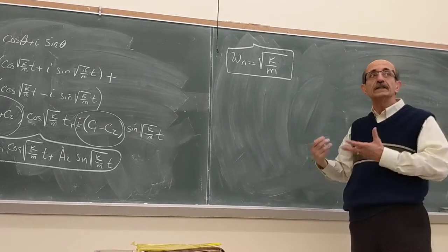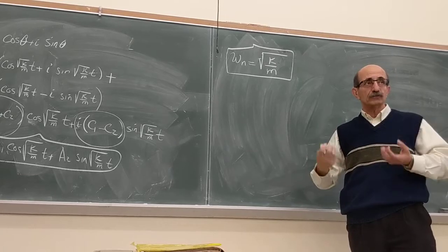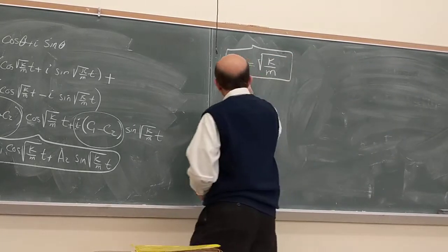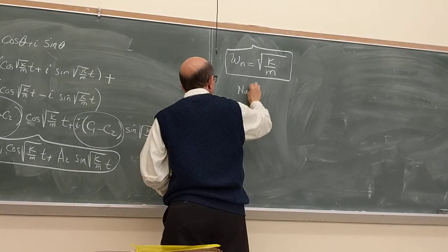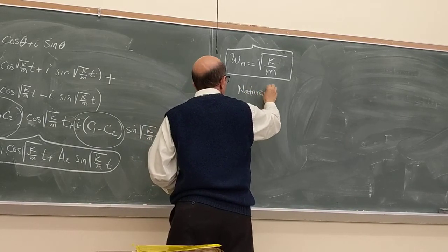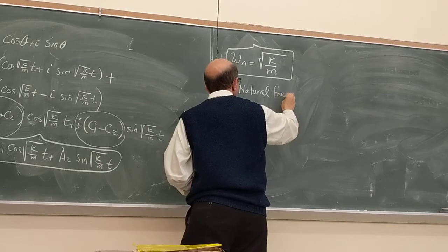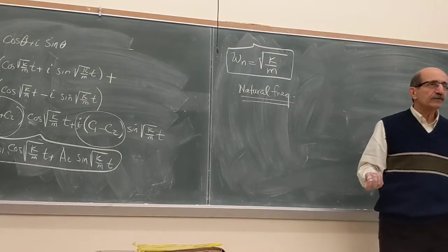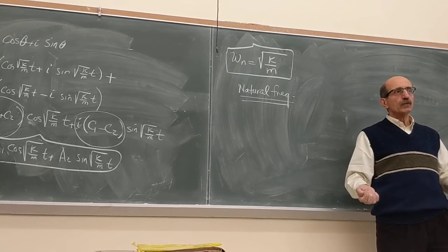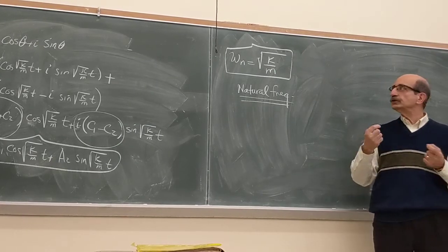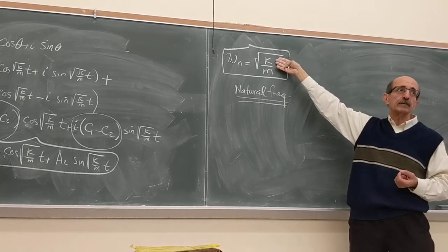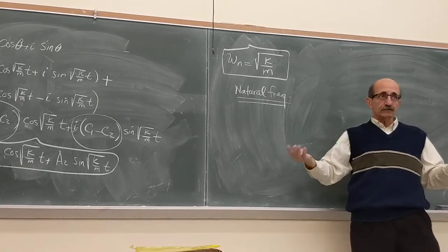Since this only depends on these natural inherent characteristics, we call this the natural frequency. So as you can see, every system in the world has its own unique natural frequency, because every system has a different stiffness capability and a different inertia.